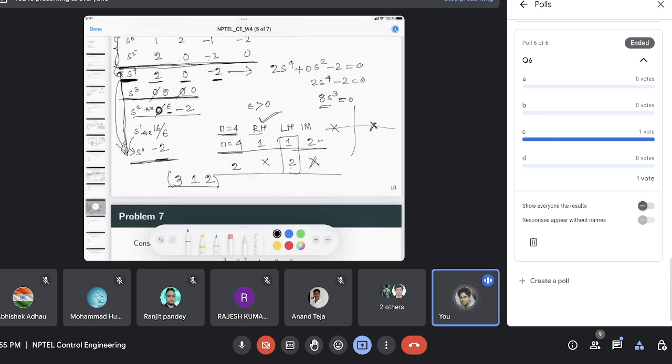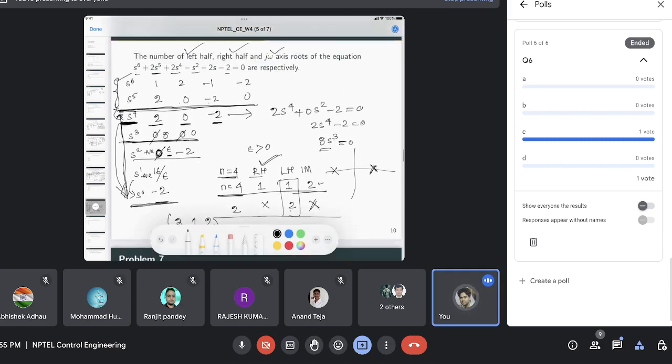Okay, just to recollect what we are doing: you write the Routh-Hurwitz table. Whenever you want to find imaginary axis poles, you must have a row of 0; only then can imaginary axis poles happen. You see that the S3 row is 0, so your auxiliary polynomial, which is always an even order polynomial, is the one just before it, that is S4.